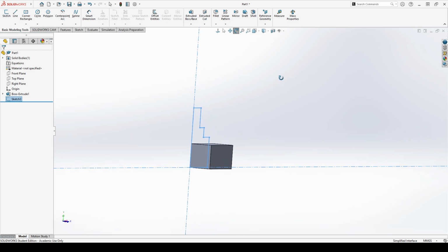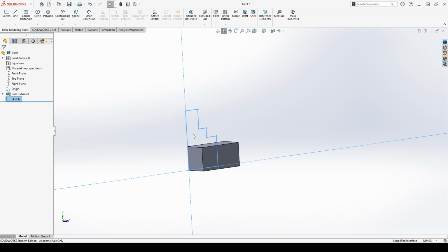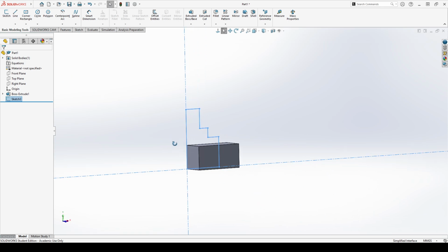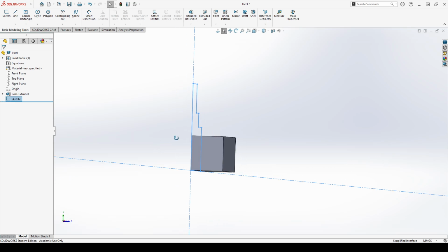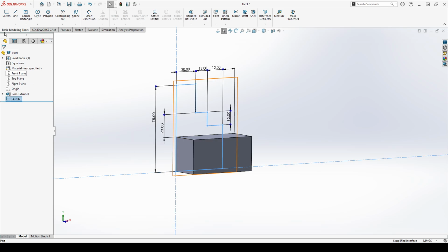Okay, so one thing to note here is I don't have any hollow or holes over here, so I don't have to worry about this pad coming out interfering with this pad. Also the volume doesn't become double. It's just treated as the same thing. So you can either start the sketch here or you can go all the way to the bottom. It doesn't matter for now.